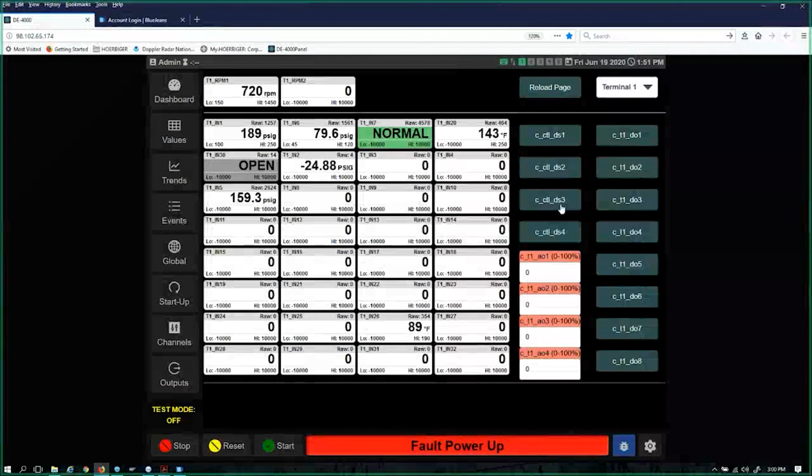What's the one thing we do when we build a brand new package, when we've just gone through and overhauled the compressor and the engine, and it's something that we're controlling the starter on? It's natural. Like, we want to spin that thing over with the starter first before we ever put any fuel or ignition to it, right? To make sure that nothing's bumping.